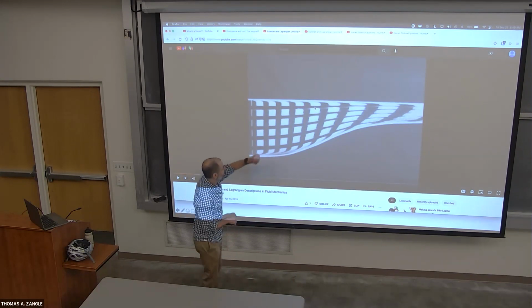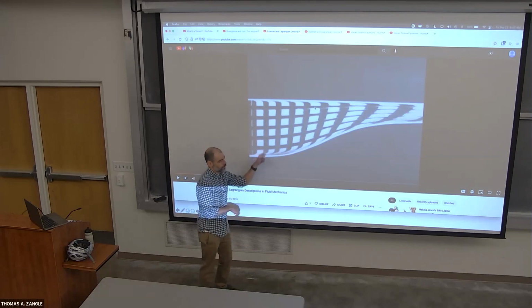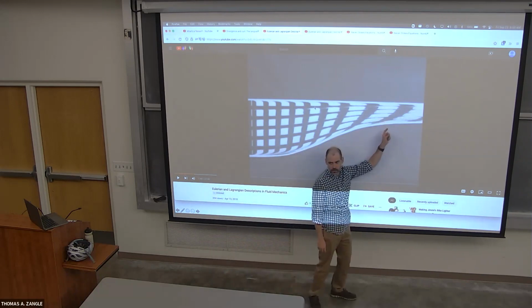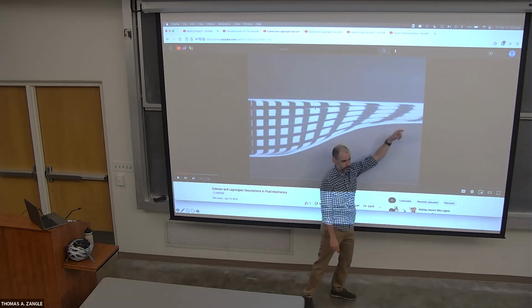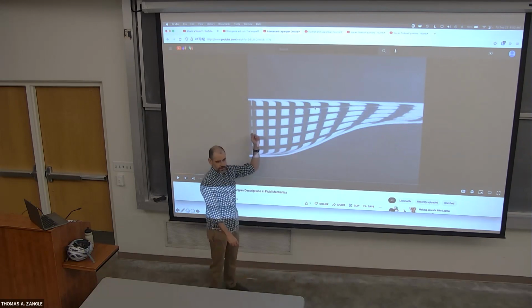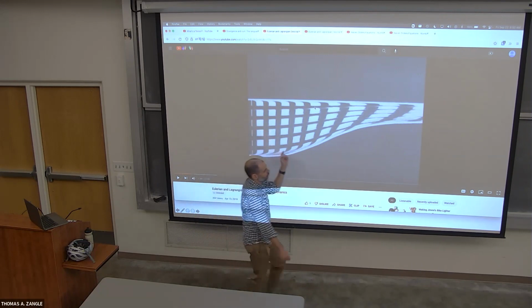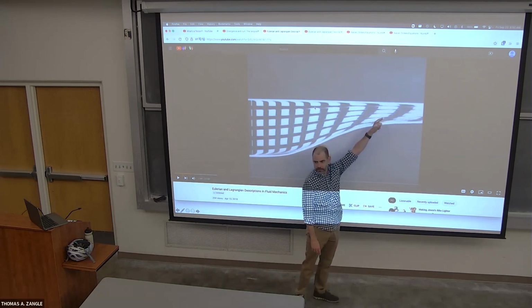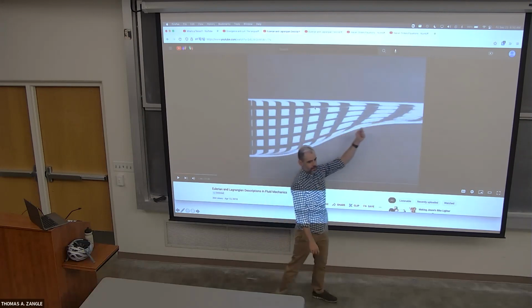But we know by mass conservation that the area here is larger than the area here, meaning the velocity at this outlet has to be larger, right? When the area is smaller, the velocity is larger than the velocity coming in, to conserve mass. And therefore a fluid parcel, we just look at this little square here, has to accelerate as it moves up and through this end. It's going from low velocity to high velocity.